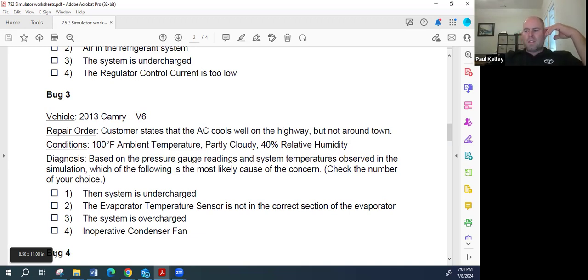In a lot of ways, maintenance is one of the reasons it breaks anyway. Now, this golf cart had a completely non-maintenance related failure. This had a bad charging port. And the charging port would basically signal the computer that the charger is plugged in. If the charger's plugged in, the cart doesn't move. That's a safety feature. So I could have done all this maintenance and it still wouldn't have moved. And then a lot of people like to blame the customer, saying, well, you didn't do something. It's got to be your fault. But the maintenance had nothing to do with the charging port failure. The charging port failure was just parts go bad.